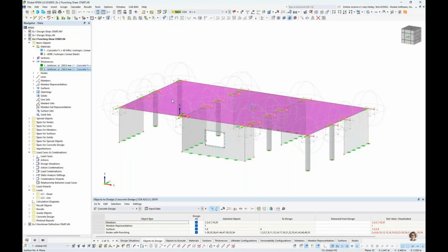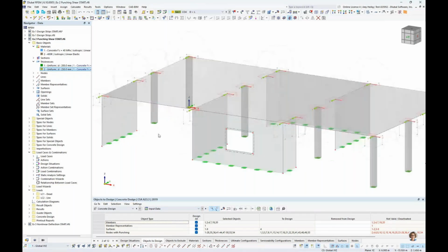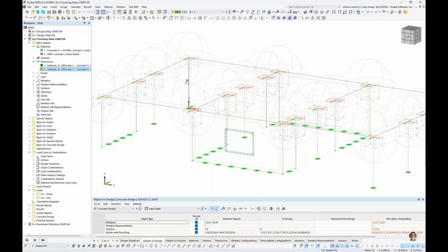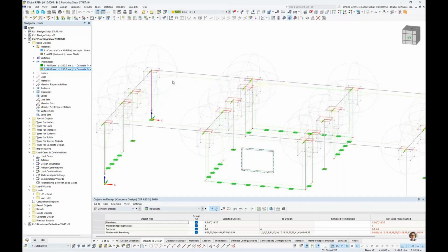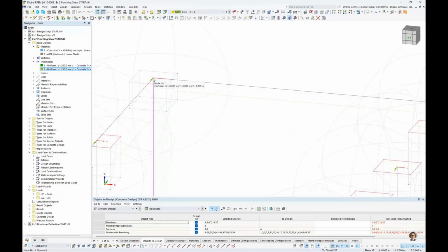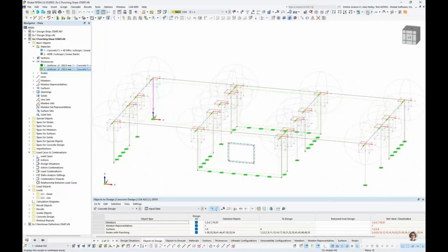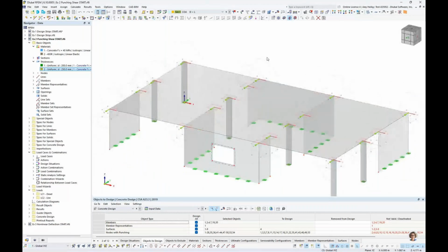But because I'm going to carry out the design according to the FEA method of this elevated slab, inevitably we're going to have what we call singularities. And singularities are not unique to RFEM. They happen in all FEA programs. And the reason why is because we have these column elements, for example, that are framing up into the 2D surface, and all forces are being transferred at this single FE mesh node. But we know in reality, we're certainly getting better load distribution than just that single mesh point, because our column is certainly going to have dimensions here.